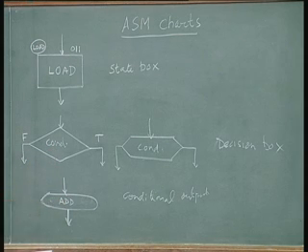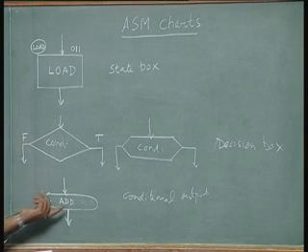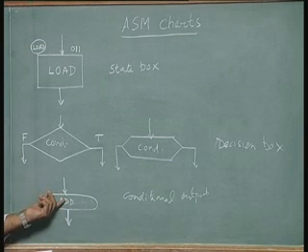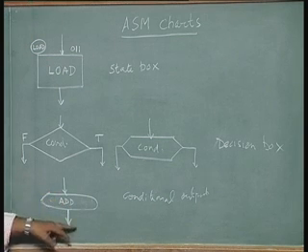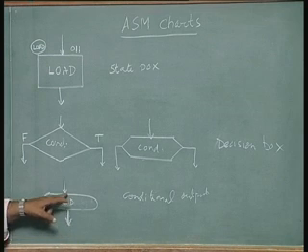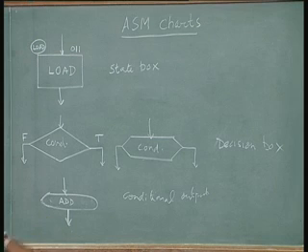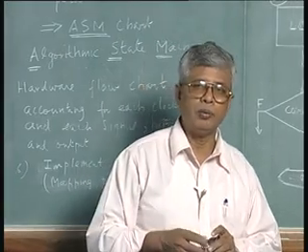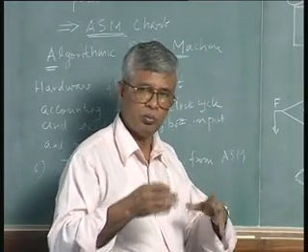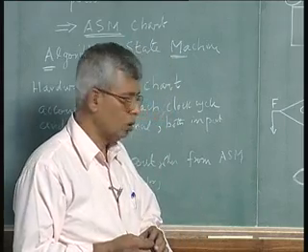This is useful. Otherwise, what we have to do is to put an extra state. Now, after this it can go to this, generate this add signal and go to the next state. If you do not have the conditional output, I may have to put one state for add and then next one more state for shift, which means I will put one extra state. If you keep adding the number of states, the mapping hardware becomes more and more complex. So, to avoid that we have this.